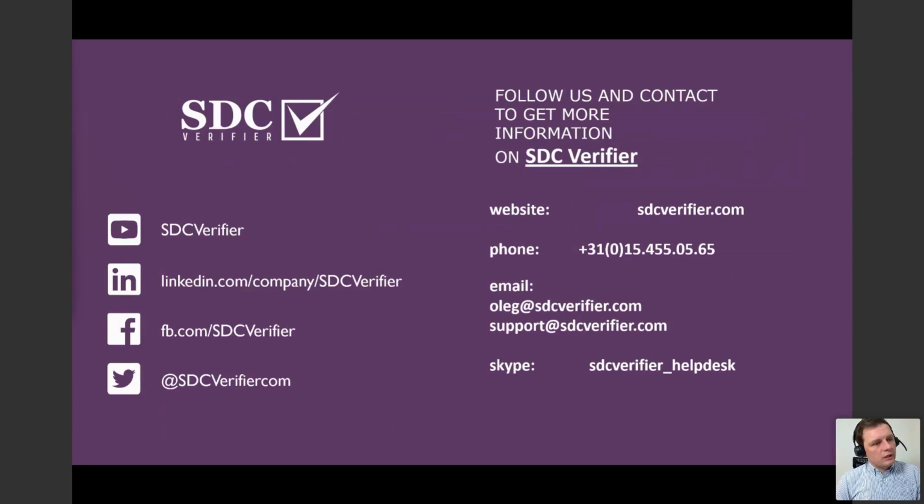I was working with my colleagues from the rail industry demonstrating some of the codes for them. We have a customer, I'm not sure if I'm allowed to name them, so I will just say that they use SDC Verifier in Europe for railway car design, and there are a couple of common codes. If we speak about the welds, there is the German standard FKM, but there are even more common standards, DVS 1612 and 1608. One of them is for steel, another one is for aluminum.